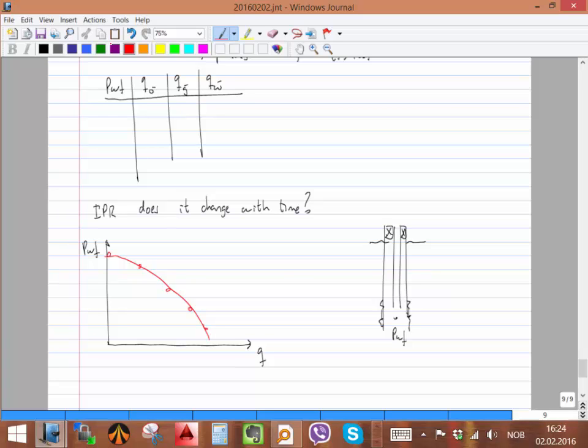The shut-in pressure first: if I close the well, the pressure will have a lower value, right? Because I have less material in the reservoir. So the reservoir pressure PR1, at time 1, is greater than PR2 at time 2. But the IPR, you say it in general because the IPR is actually the curve. So the IPR is changing for each depletion stage.